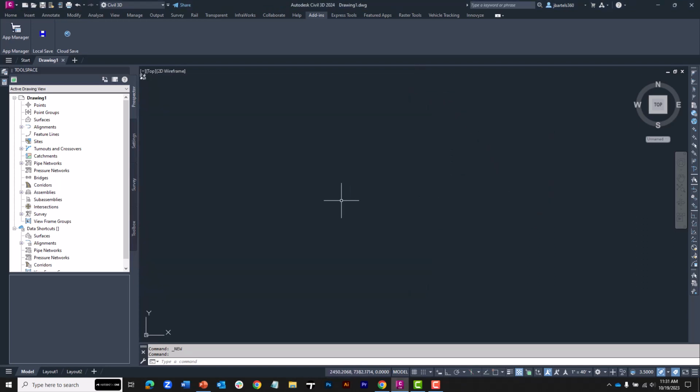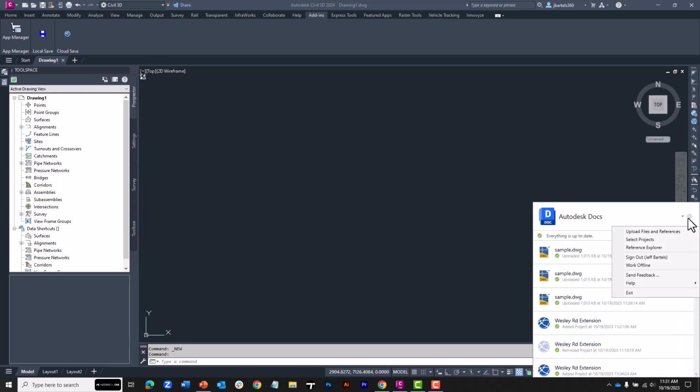One more thing. Remember that Desktop Connector represents the conduit between your local environment and the cloud. There could be a lot of moving parts there. Everything from obscure antivirus applications to internet bandwidth to local IT protocols can affect the performance of Desktop Connector. In the event you're having challenges with Desktop Connector, what you can do is come down, click the icon, click the gear, and then come down to Help and choose Diagnostic Logs. Desktop Connector maintains a log of all the transactions that it has back and forth with the cloud, and it will include additional information, specifically places where it's having trouble.